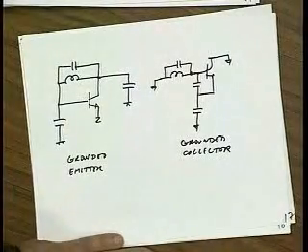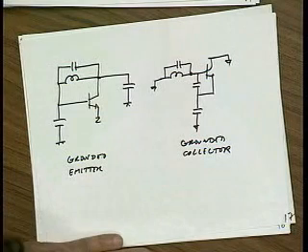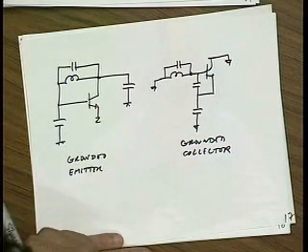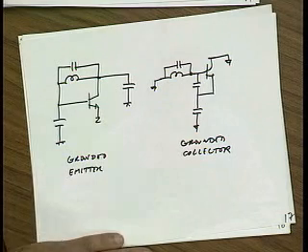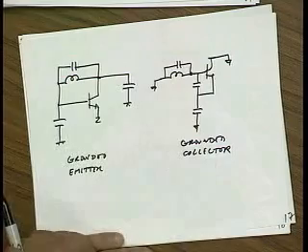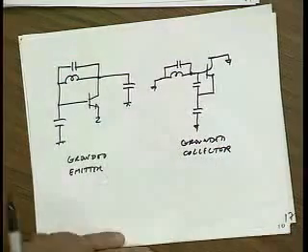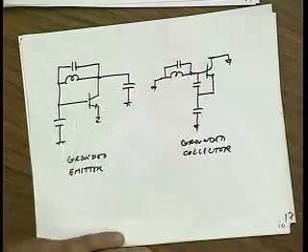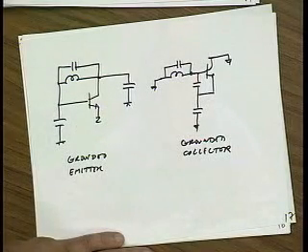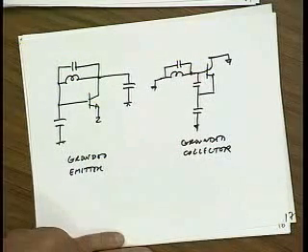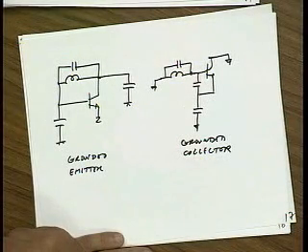Like there's no difference on loading from the transistor or... No, there is. That's the key point. Because when you ground the node, for instance here, I'm grounding the emitter. So obviously the emitter is not going to load my circuit. So where I place the ground will have a big impact on basically the loading and the feedback factor. But as far as the circuit goes, it's really the same circuit. The emitter points moved around. Okay?